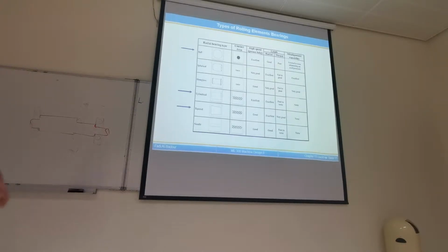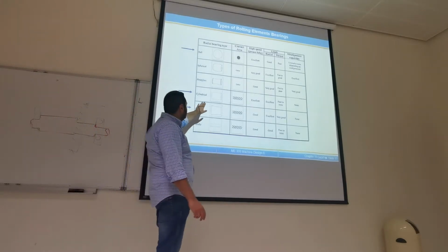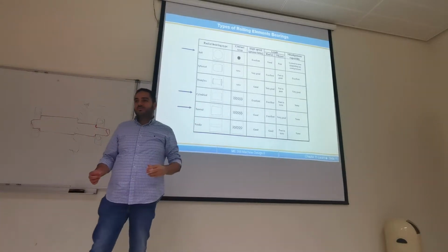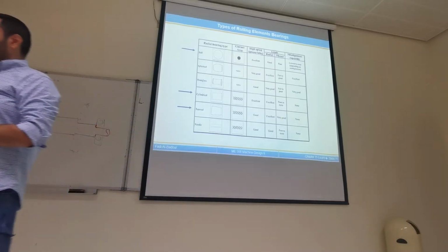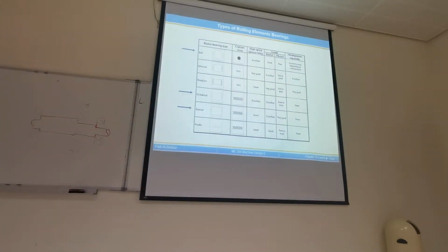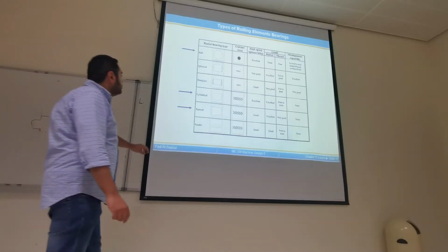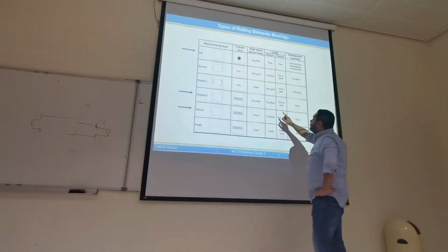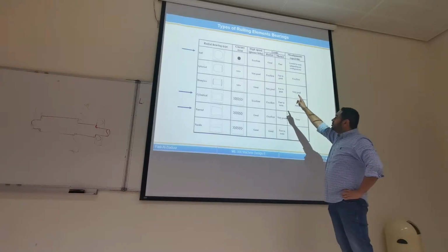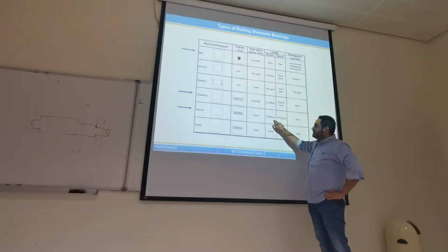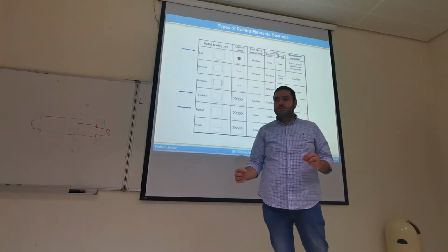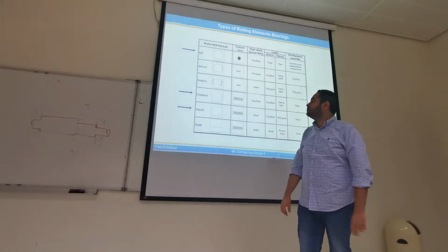But if I have a cylindrical roller like this, the contact surface will be bigger now, and I will have a line contact. Same thing for tapered roller. So, due to the contact area, the radial load capacity for ball bearing is good, but for cylindrical and tapered is excellent. Why? Because they have more contact area.